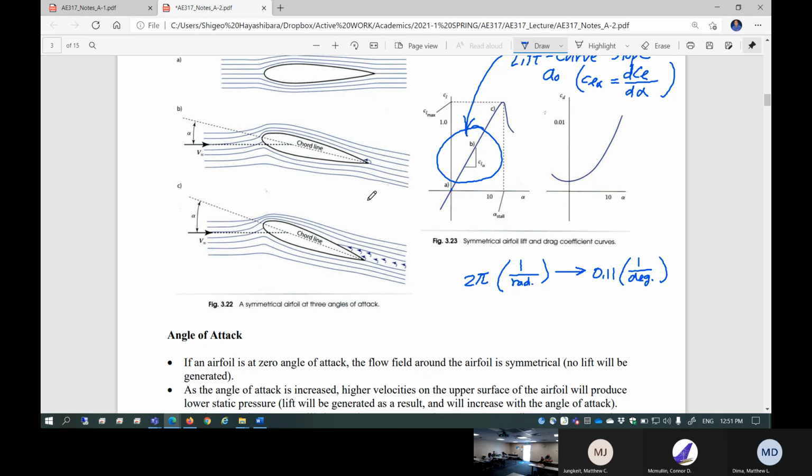But it is true, if you make a poor decision at the very beginning, your airplane sucks, and there's not much you can do to fix it. In other words, my airplane is a supersonic airplane, but we decided to go with this super thick cross section. Wait a minute. No matter what you do, your airplane sucks. It's not a supersonic airplane. So the basic characteristics are going to be set in rock when you choose the cross section to begin with.